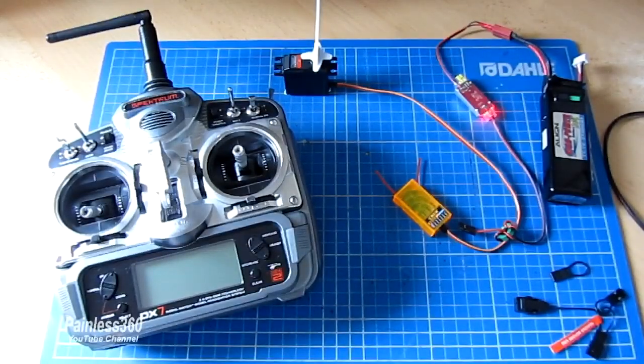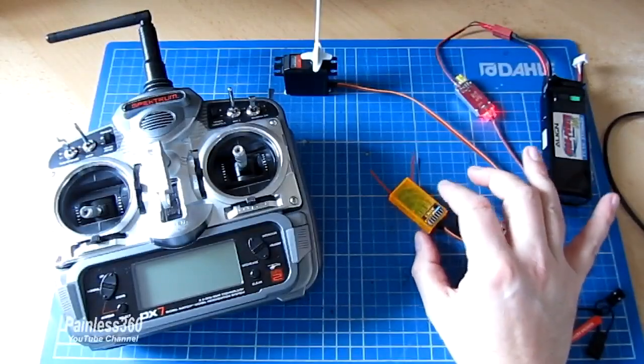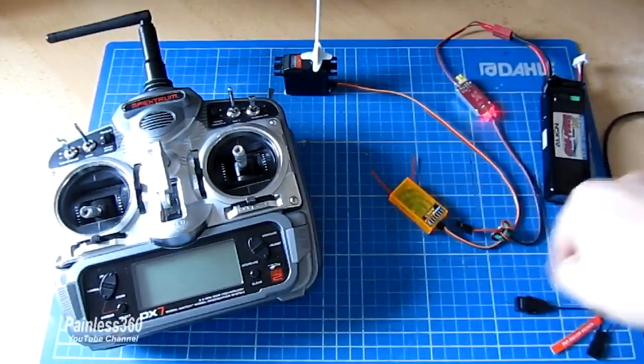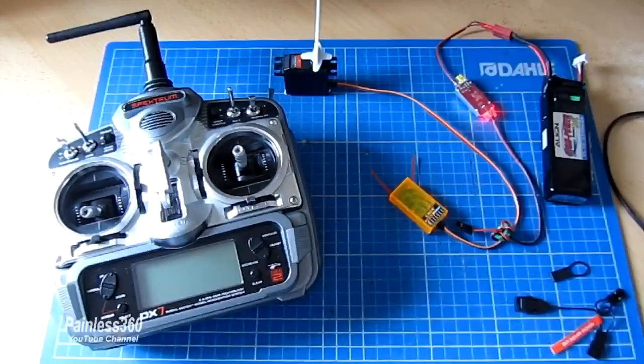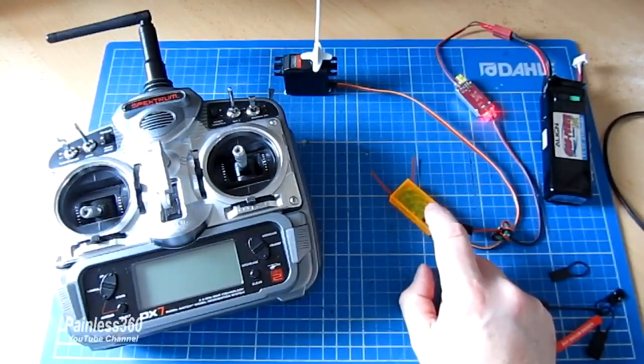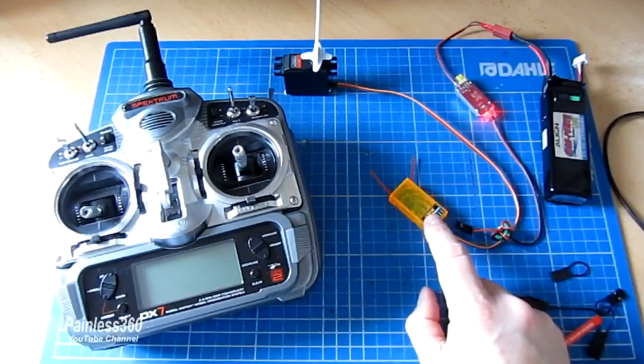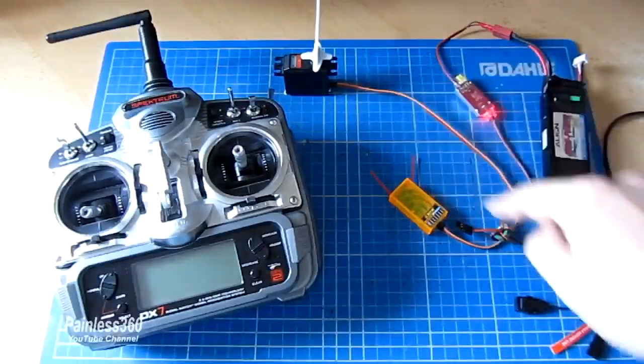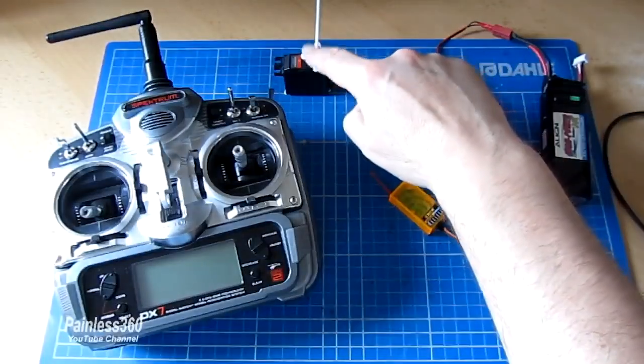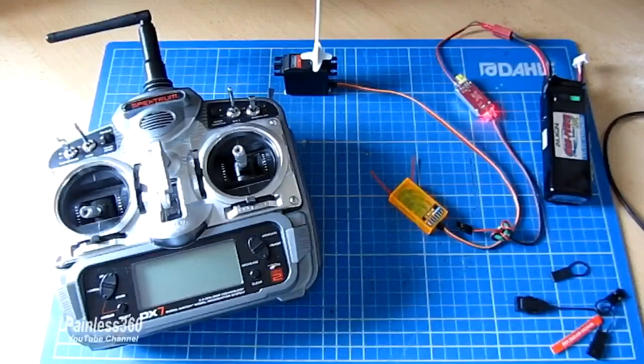Now what failsafe is: when the receiver first boots up, it has to be sending something out of all these channels while it's waiting for connection to the radio. And also, in the event that it loses the connection with the radio, like it just did while that little red light was flashing, it also needs to continue to send out a set of positions for the servos and a position for the throttle so that the plane, or whatever it is you're flying, will continue.